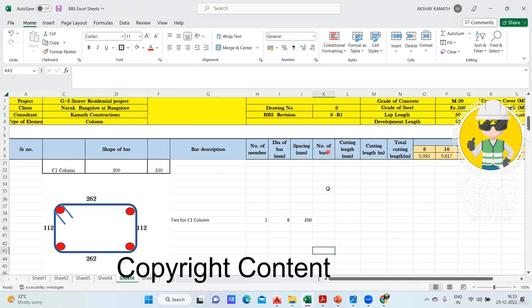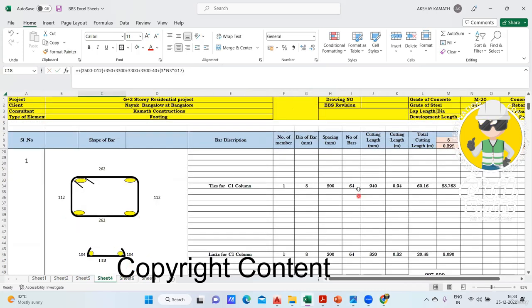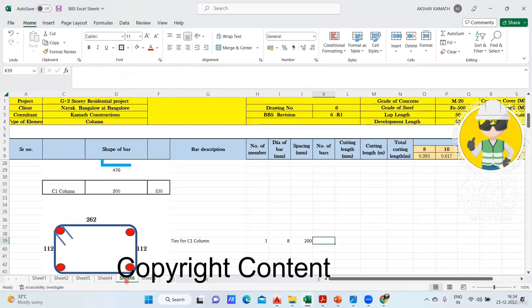Fine. And that's it. Now how will we find the number of bars? You know how to find the number of bars. I already taught you how to find the number of bars. Okay, I'll not do the same thing. You have understood, no? Number of bars, you have to round up. 2500 minus 50 minus bottom dia, shorter and longer. Then plinth beam height plus 3300 plus 3300 plus 3300 minus 1 cover, divide by spacing. Anyhow, I'll do that.